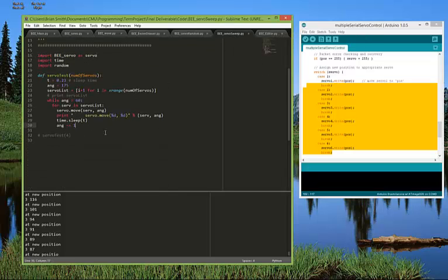And then servo sweep, which is actually one that will be really useful for the plaster work. Basically it just starts at 175 and goes in increments of 1, and right now I have it set to 60, but it can go all the way to 0. And that's basically what the servos would be doing as the robot is moving the trowel across the plaster, slowly sweeping through all its motions.